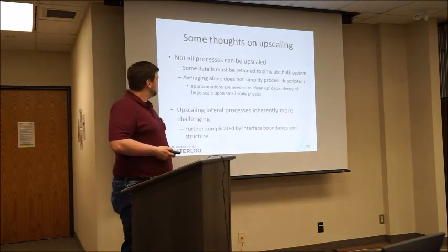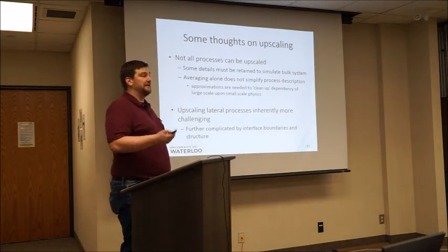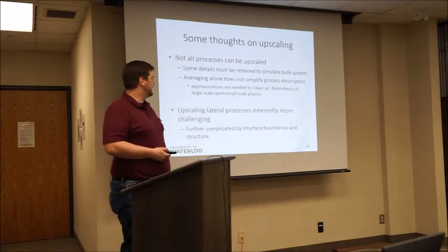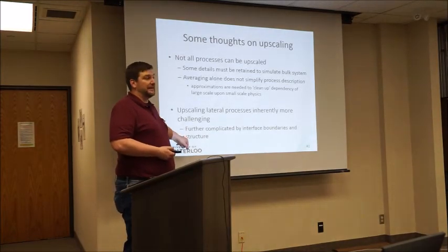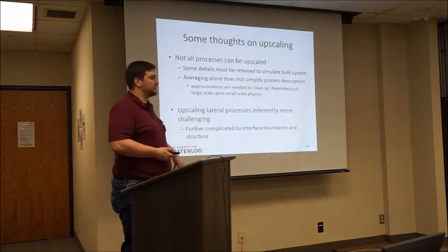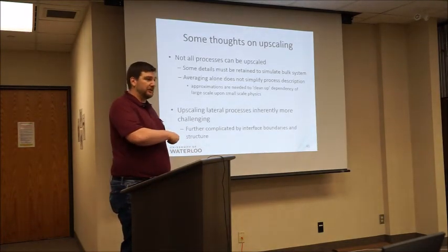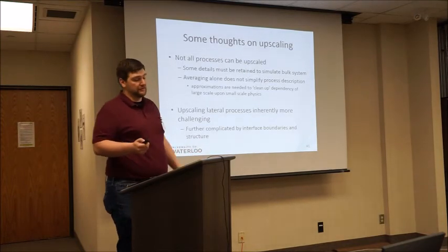Upscaling lateral processes is inherently more challenging, which is why we have to turn to some of these tricks that I showed here with the data mining and whatnot. And this is further complicated by things like internal boundaries and structure, which sometimes you can ignore in groundwater upscaling, but not when you talk about surface water systems.